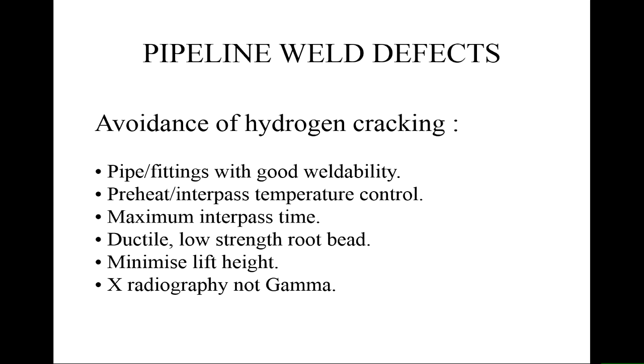While cold, and that's particularly important for hydrogen cracking, usually appears some time after the weld has been performed. Sometimes hours, it could be even days. That's why it's good for the inspection to wait some period to carry out the inspection, in case any hydrogen cracking developed.